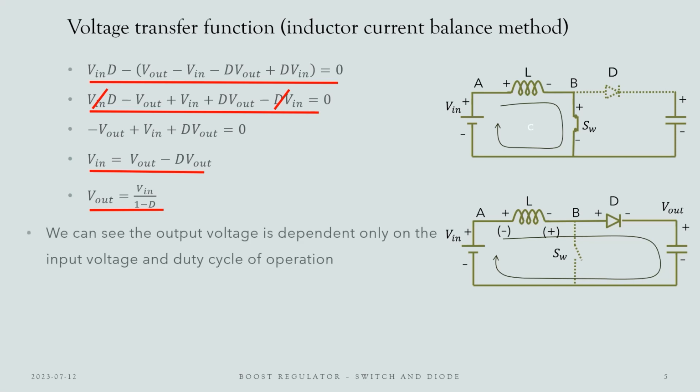Here we can observe that output voltage is dependent only on the input voltage and the duty cycle of operation. It is independent of inductor value and switching frequency.